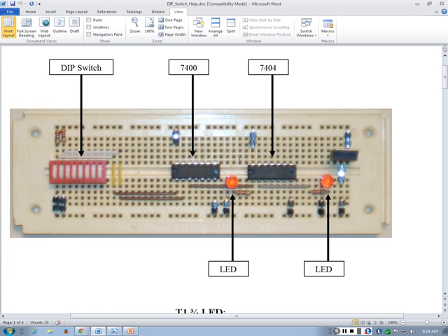And also, if you look at the ICs carefully, as we said, pin 7 has to be grounded. Look at pin 7. For each IC, you see we grounded them. This is just a wire we ran to short it to the ground. And also, each pin 14 is connected to the voltage, which is VCC here. Because this column is shorted, right? So you can just run a wire from any of these points.